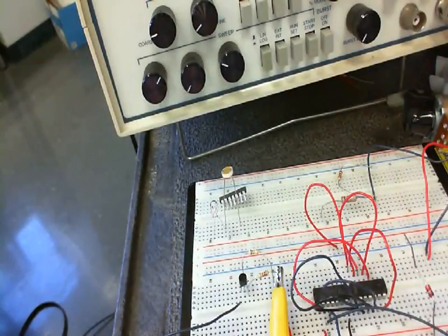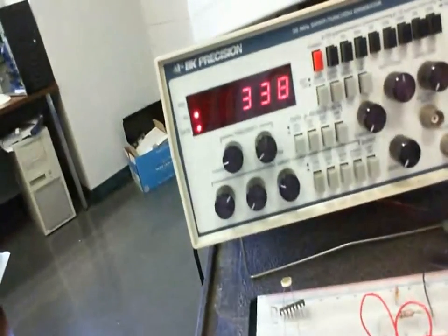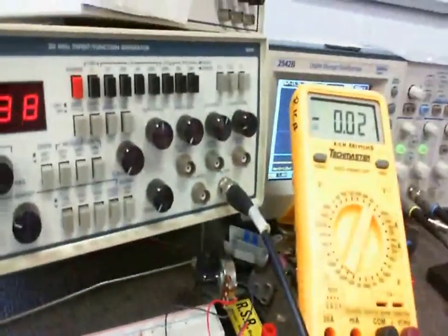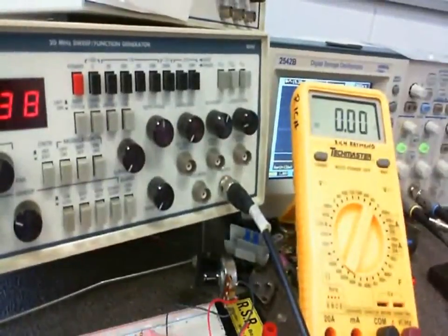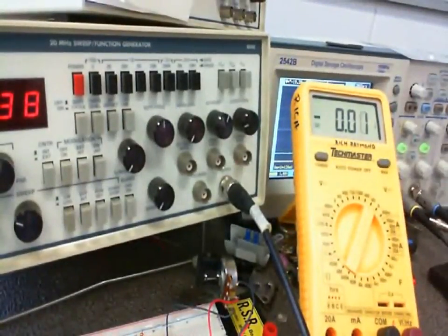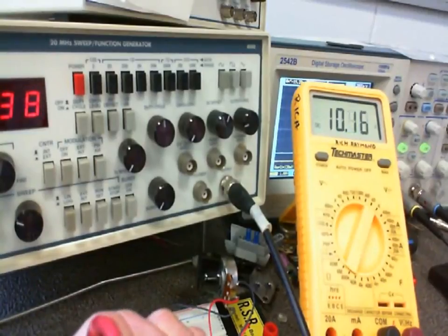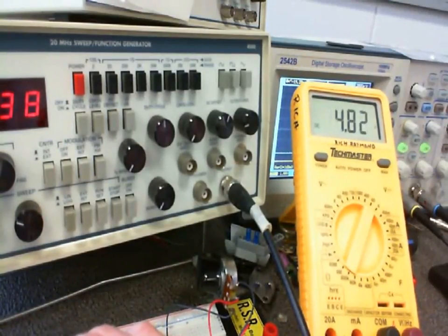And what was the voltage we calculated on the collector, collector to emitter? That was depending on a beta of 100. So when I look at this one, I measure my collector, and there's the power supply. It's measured 4.8, which is not bad, right? You understand? We calculated what? 5.7, so we're off about a volt.